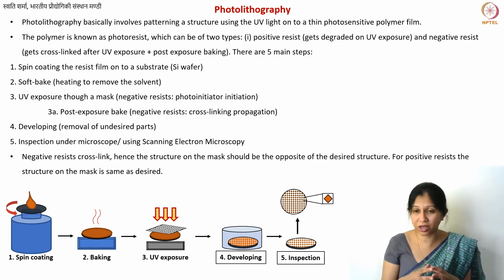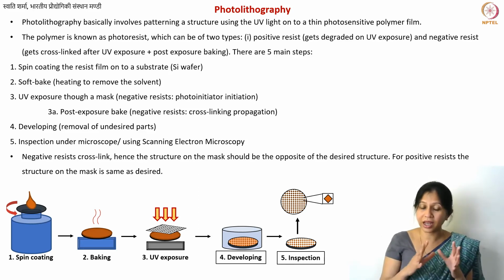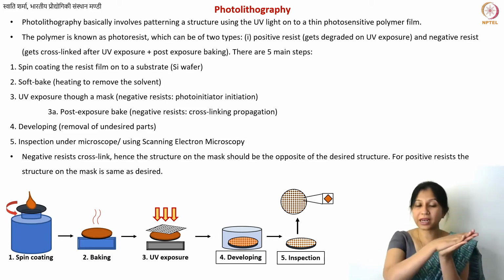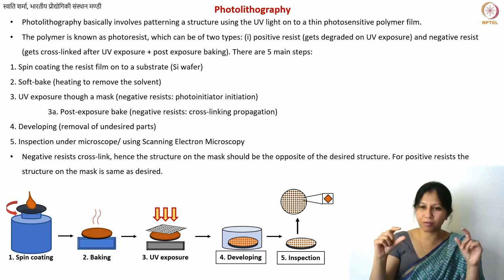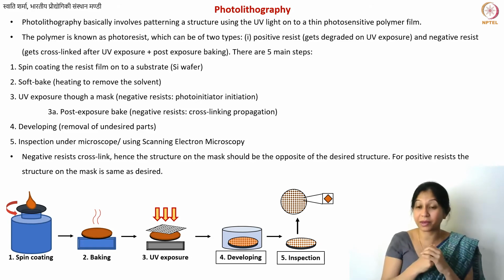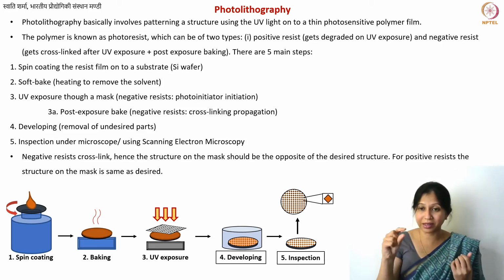You can make very small structures, and different types of mask fabrication techniques are also available. The optics of these instruments is also very interesting. You can have complete contact of your masks. Sometimes you can also have some proximity, where your mask is in the proximity of your wafer but not completely touching. You would do that in the case of a polymer where you cannot avoid a certain liquid part, or the polymer does not become hard before the exposure, so you don't want to attach the mask to it.